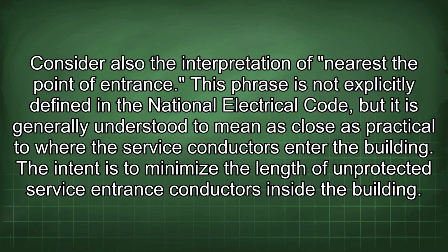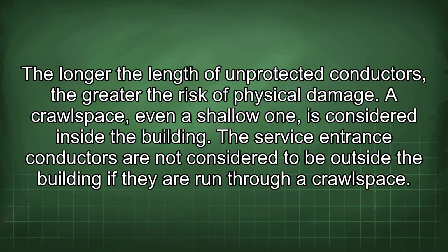Consider also the interpretation of "nearest the point of entrance." This phrase is not explicitly defined in the National Electrical Code, but it is generally understood to mean as close as practical to where the service conductors enter the building. The intent is to minimize the length of unprotected service entrance conductors inside the building. The longer the length of unprotected conductors, the greater the risk of physical damage.